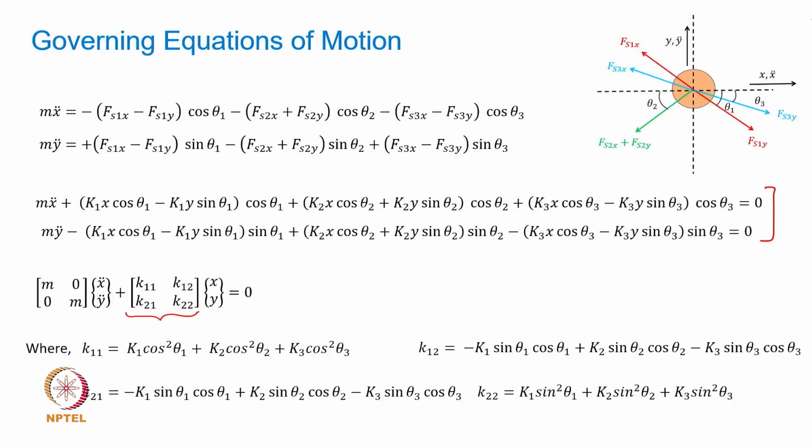This is true because if you try to move this mass in this direction, there are going to be unbalanced restoring forces acting along the x direction as well because of this motion along y, and therefore any y motion is also going to generate x motion. Similarly, vice versa, any x motion will generate some y motion because of the peculiar configuration of this particular system.